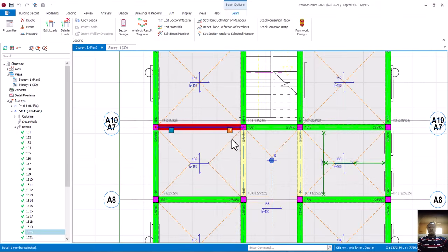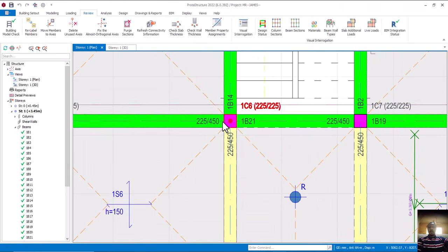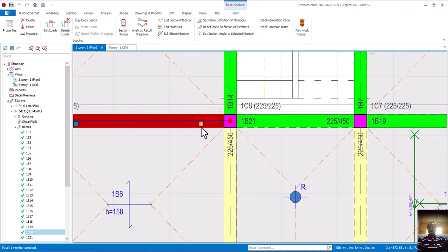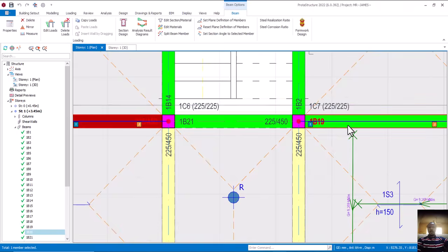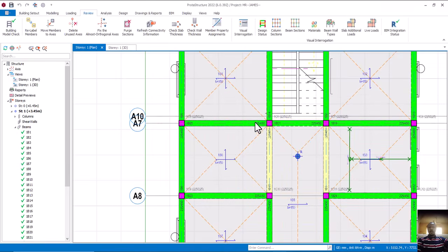And that's why if you now look at the J side, you can see this beam resting on this column and also continuing. There's another beam continuing from this place, which is beam 21, and also beam 19, etc. So if you have to draw the bending moment of this place, definitely our moment will start from this point here. Is that okay?